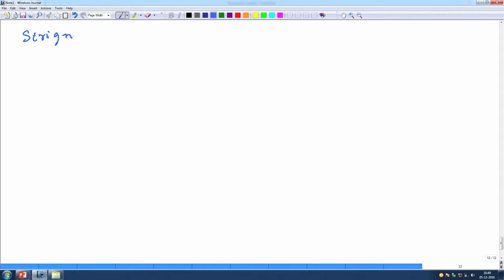In the last class we mentioned the modified Nusselt number and Sherwood number in this particular case. Now let us look at the form of this f, which we already mentioned in the previous lectures. Here we will once again, for the sake of completeness, reiterate that. This is Abramzon and Sirignano's model essentially.